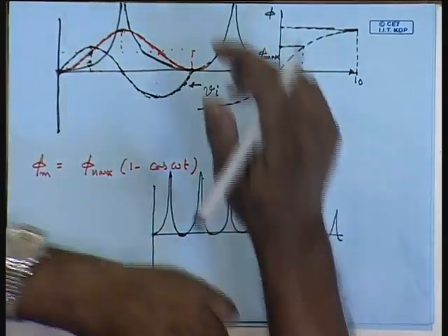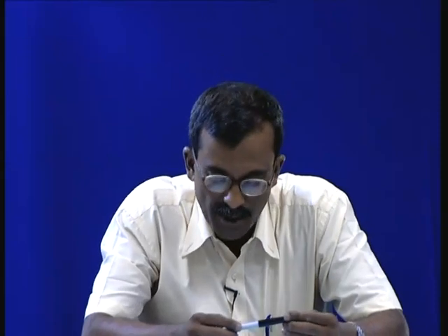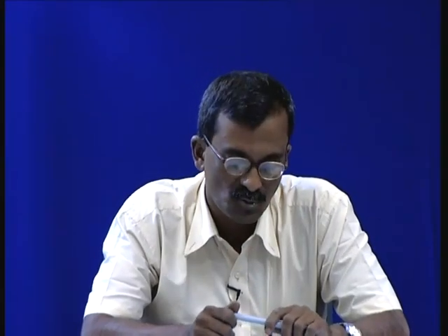So, depending on when the transformer is switched on, it is possible that there will be a magnetic inrush in a single phase transformer, due to which the no load current of the transformer can rise to dangerously high levels for the initial few cycles. The protection system should be designed to handle this, because it is difficult to precisely determine exactly at which instant a transformer will be switched on.